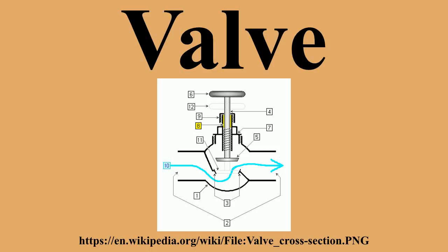Handle or actuator. A handle is used to manually control a valve from outside the valve body. Automatically controlled valves often do not have handles, but some may have a handle anyway to manually override automatic control, such as a stop-check valve. An actuator is a mechanism or device to automatically or remotely control a valve from outside the body. Some valves have neither handle nor actuator because they automatically control themselves from inside. For example, check valves and relief valves may have neither.